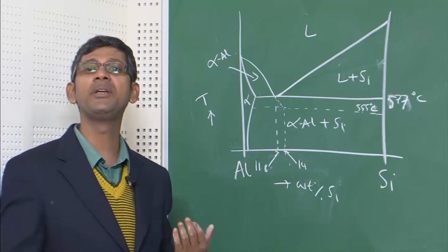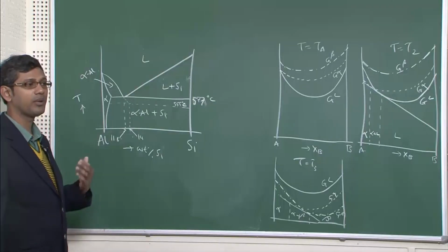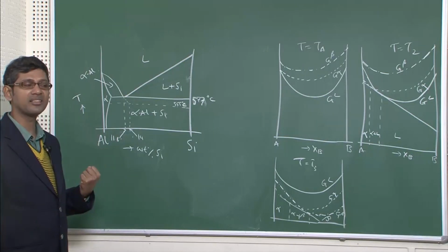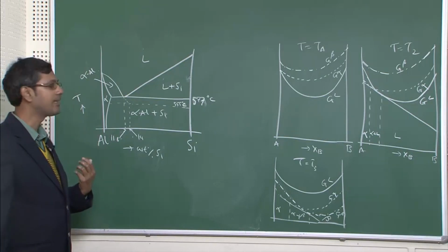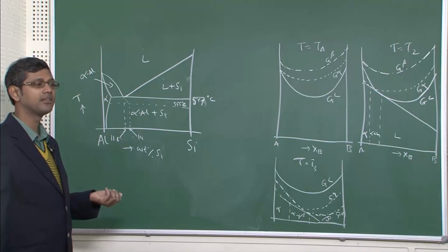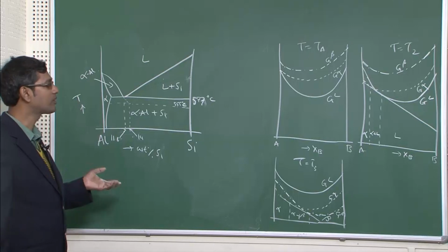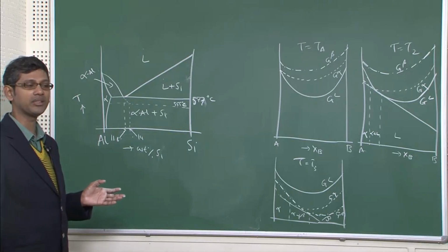And as you know, aluminum is actually a very soft metal, so aluminum dendrites will make this alloy soft, ductile and tough. At the same time, as the eutectic has become finer, it will also lead to high strength and high ductility and toughness. That is how one can explain the modification of eutectic alloys.